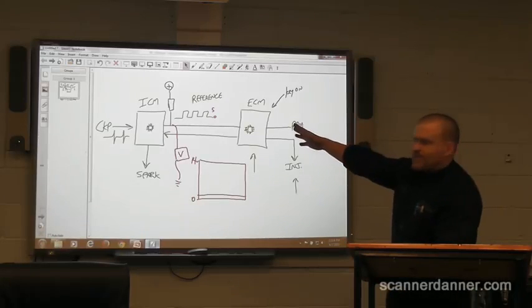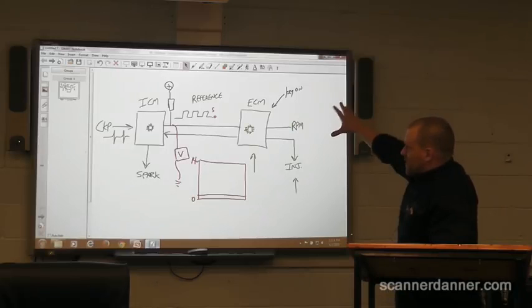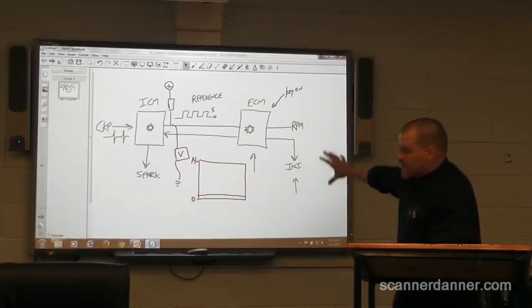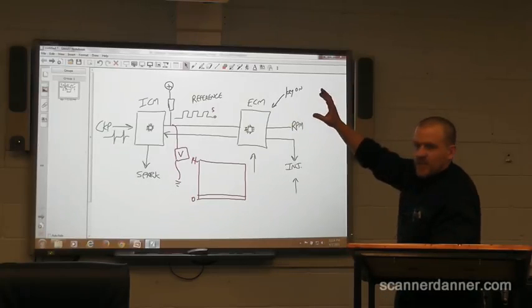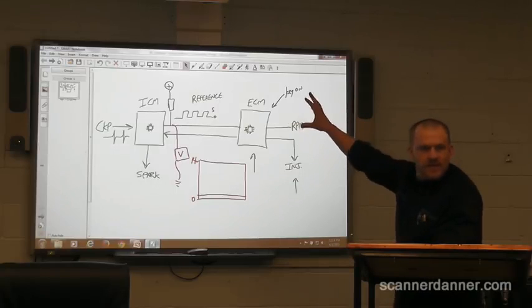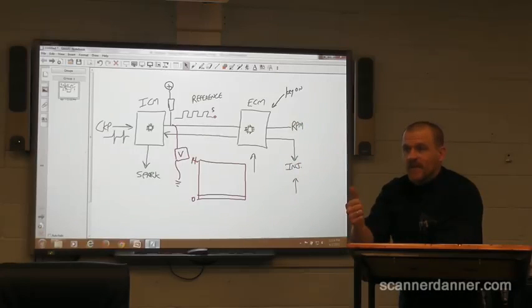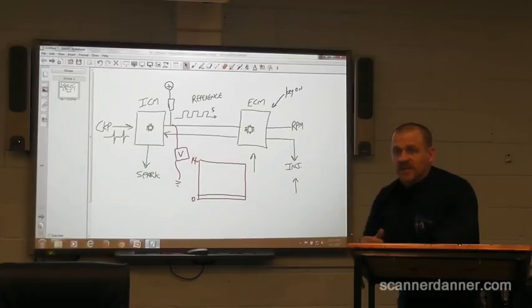That's where we are here. I gave you the reaction, the example. In my case, the injectors fired. That says what about the computer, the wiring, the injectors? It says they're good. So do you see my focus is to the left, which is the ignition module. Why is the module not sending that signal? I can create that signal.